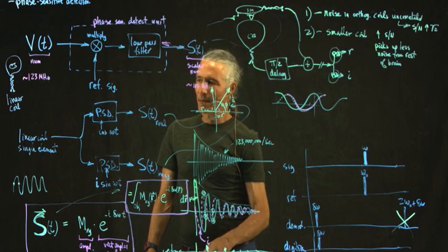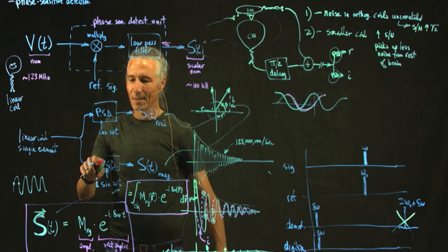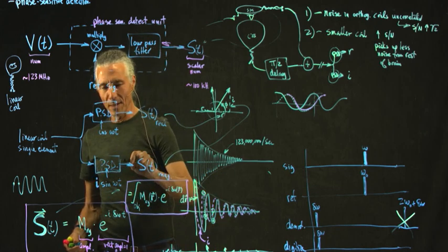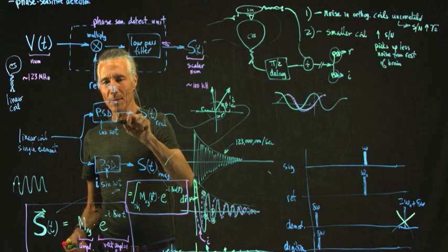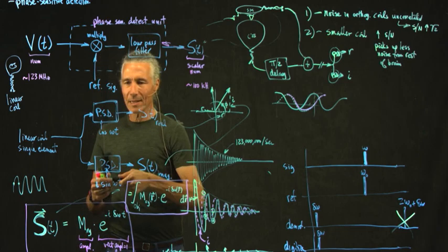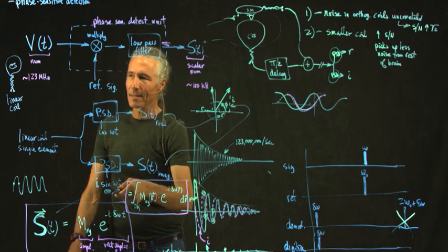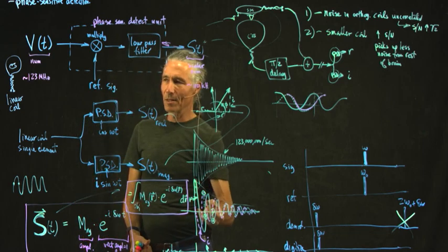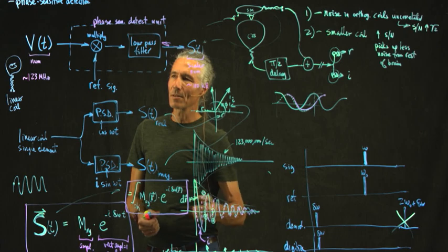And the way we get that vector is by this phase-sensitive detection business, which is take one signal and then multiply it by a cosine and a sine, and that gives us this fundamentally two-dimensional signal, which is the angle and the amplitude.